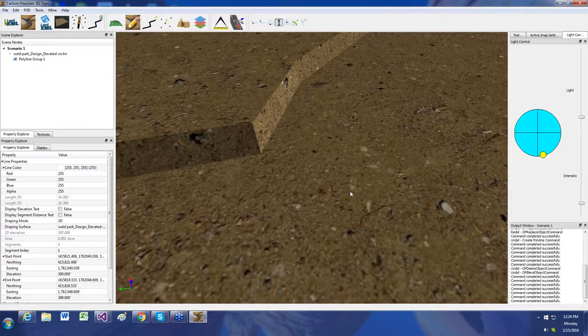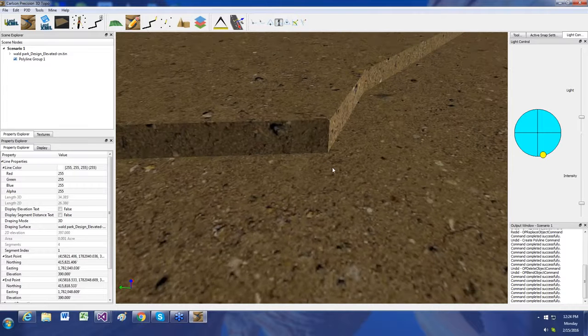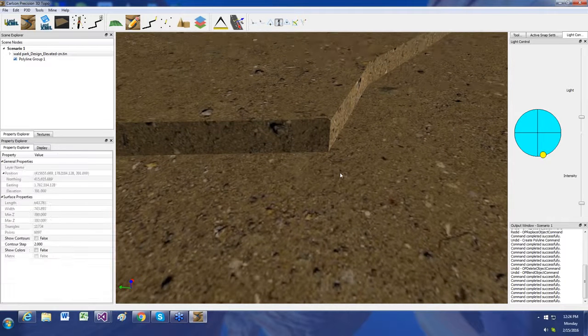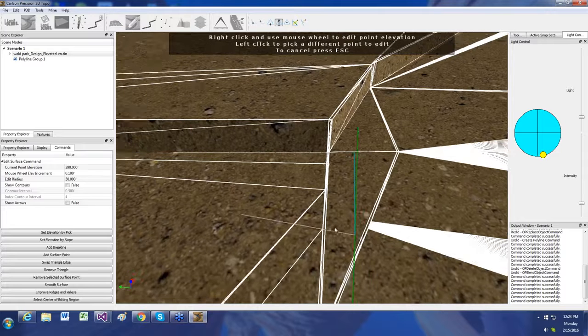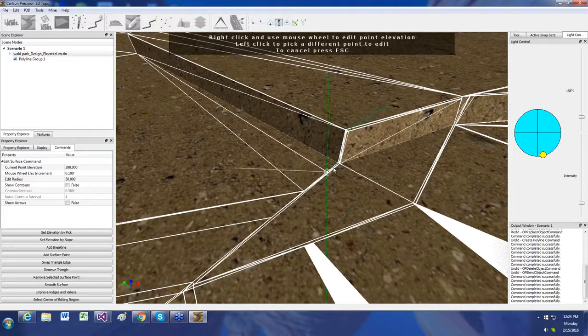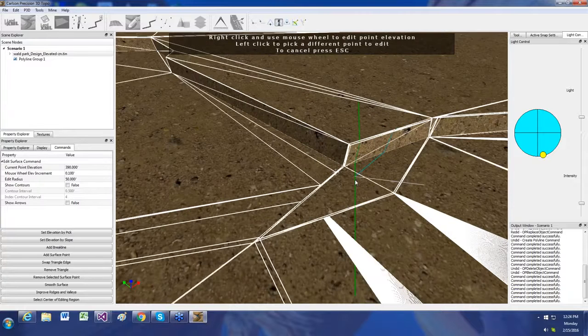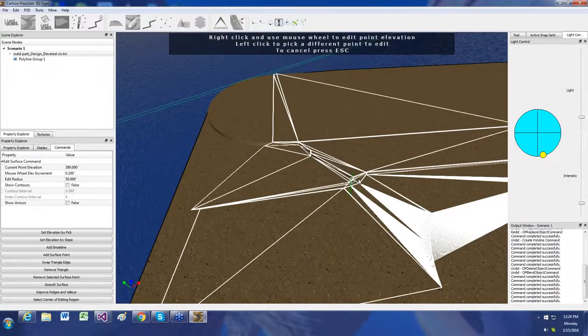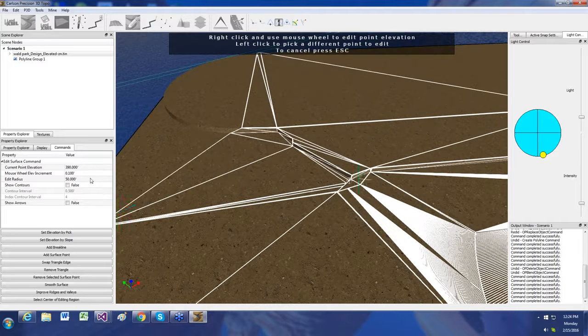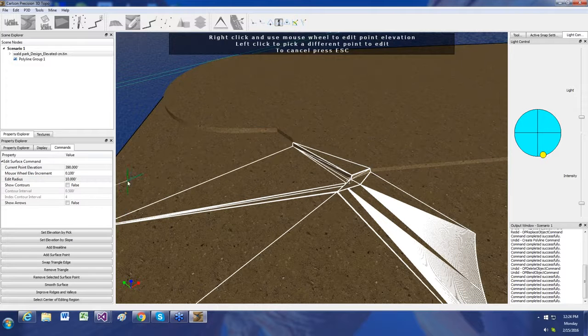So again, these node snaps allow, so if I go into edit surface at this point, what you see on the screen are dynamic graphics, and we're automatically snapping to the center point. We also limit the area of influence. So if you don't want to have such a large area of influence, you can shorten that down. So I'm down to 10 feet.